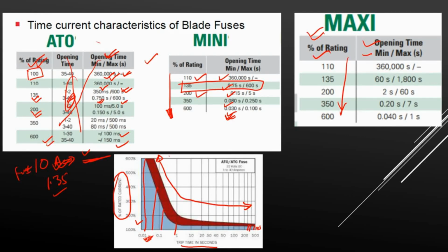So as the current increases, our fuse will blow immediately. Because the concept of fuse blowing is I square T, okay. If I increase, and the duration also increases, then the time of opening of the fuse will reduce, okay. We will understand this particular concept more in the coming slides, okay, what this rating is and all those things.